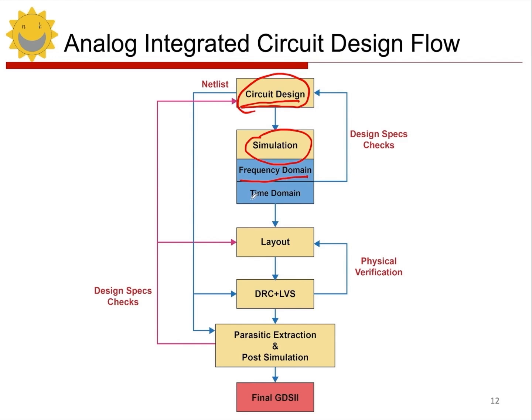The netlist, post-schematic, is used in LVS and post-simulation, incorporating parasitics to form a post-layout netlist. Perform post-simulation. If it passes, the circuit is reliable. If not, check layout issues or design margins. Modify layout or design if needed. Failures often indicate poor layout. If post-simulation passes and meets parameters, generate the final GDSII file for tapeout.